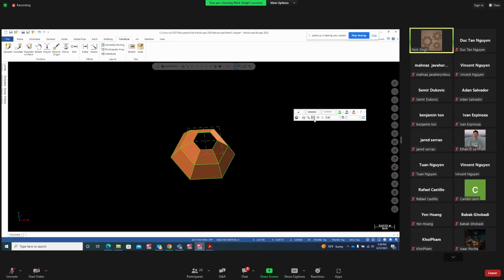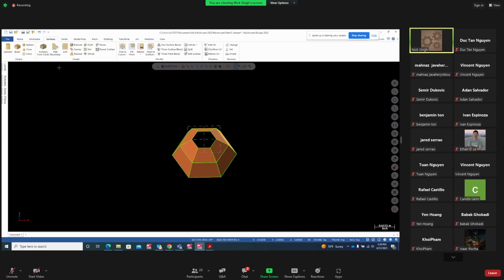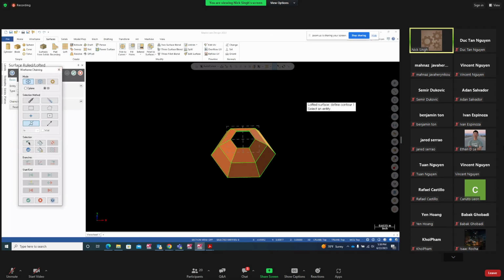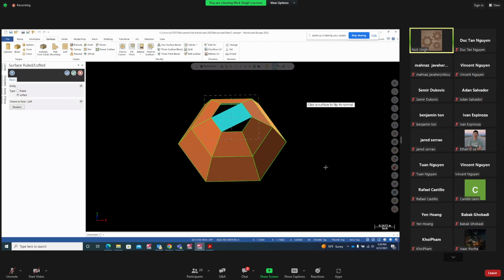Now we have to do the top hole. We have to fill up this hole. And that hole is on a flat. So if you remember, we talked about surfaces, flat boundary. You cannot use loft here, because if you put loft and you put single from there to there, it will just create a surface in between that. That's what we are not looking for.